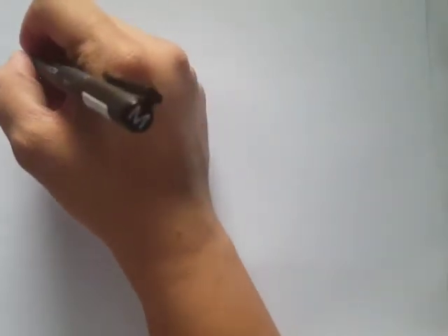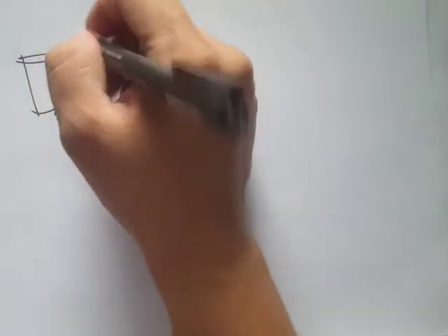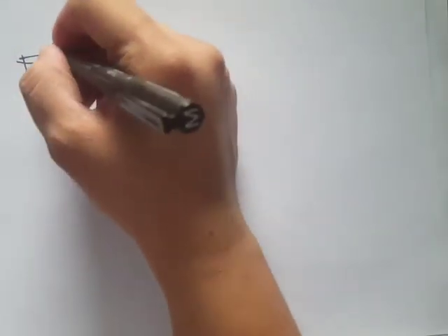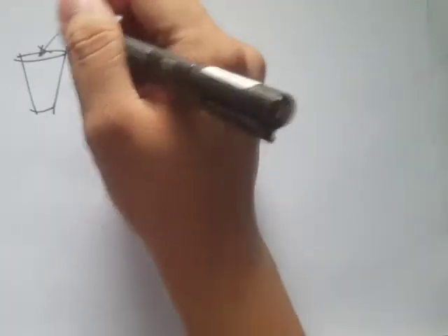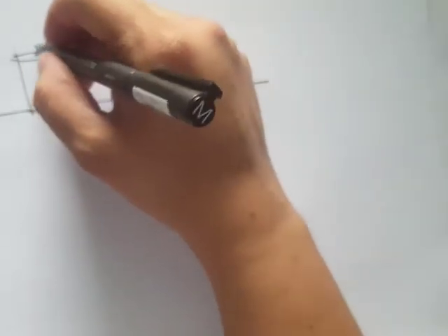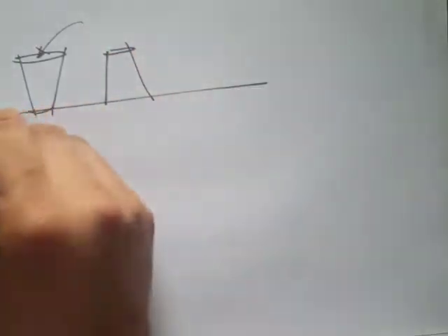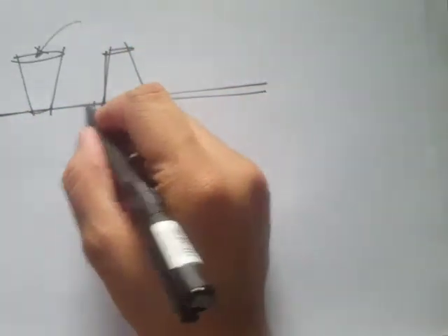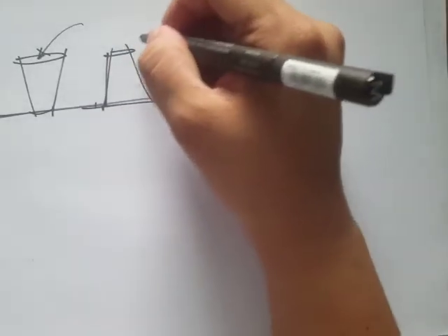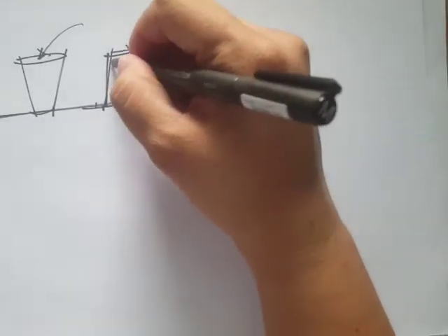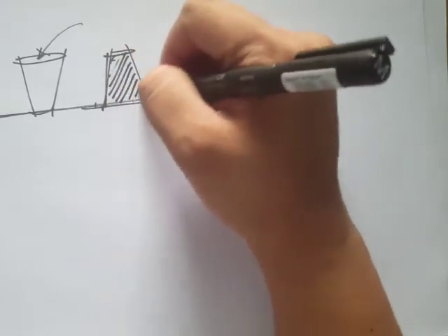Alright, so basically a slump test would look like this. You have a conical mold with prescribed, standard dimensions, where you pour your concrete mix. So it's just a sample, and after that you invert this mold, place the mix on a flat surface, and then try to remove this mold.